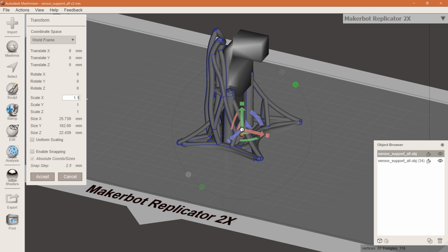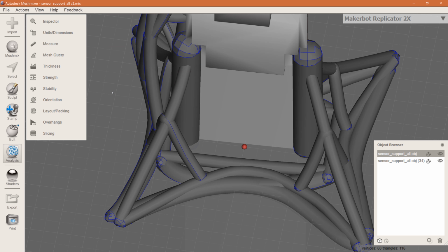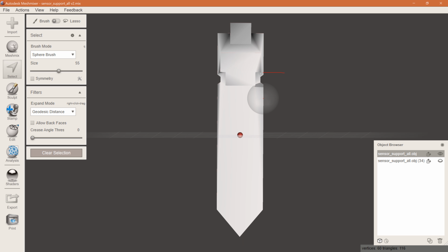So here, in the last video I talked about tolerances of parts and how it's best to do it in SolidWorks, but if you don't do that, you can scale your part in a known dimension, or in one dimension, to, in this case, increase the size of the gap that will be cut in the part.